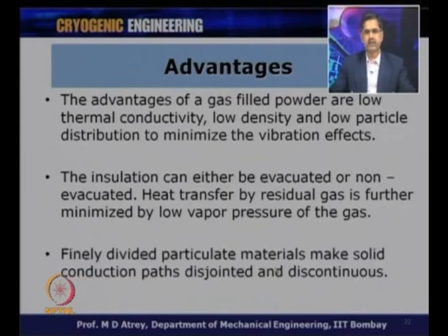Finely divided particulate materials make the solid conduction path disjointed and discontinuous, and this is the reason why these particles are used. So, all these granular particles are finely divided, and therefore this makes the solid conduction path disjointed. There is no continuous path for solid conduction, alright. Plus they have a gas also.